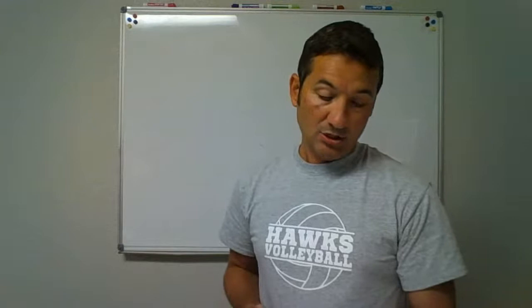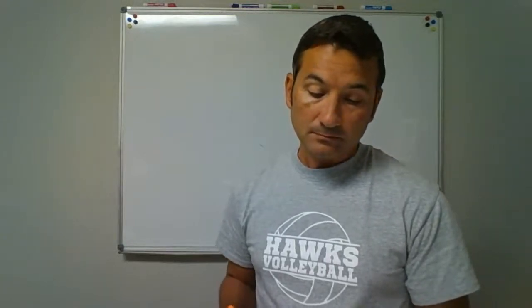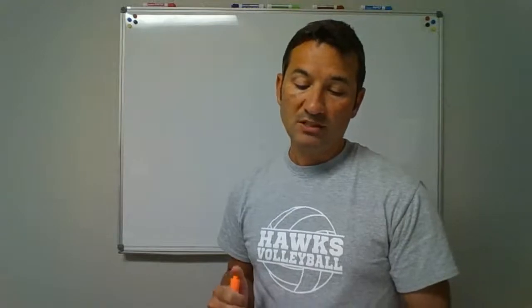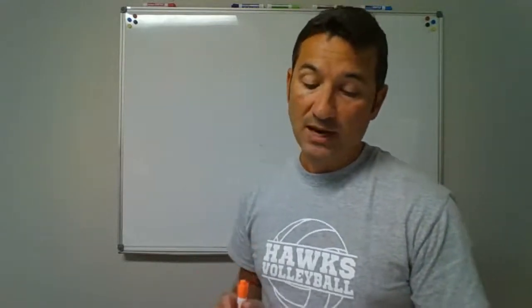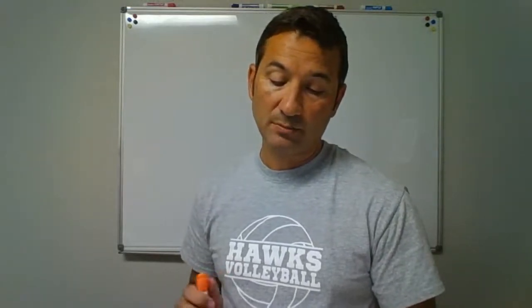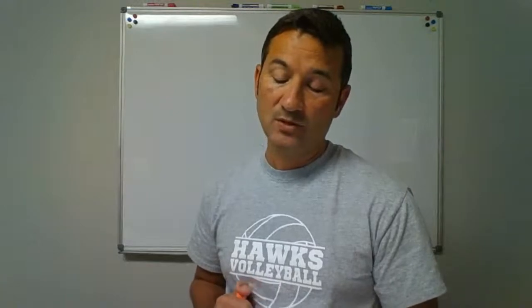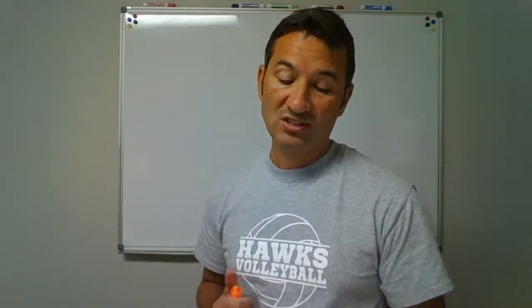I'll let you read section 302 on your own. 303, materials identification. It says each length of pipe and each pipe fitting, trap, fixture, material, and device utilized in the plumbing system shall bear the identification of the manufacturer and any markings required by the applicable referenced standards.